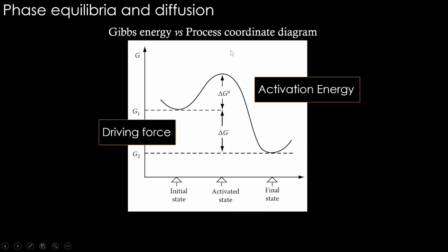Let's say there is a high concentration and a low concentration, and if the atom jumps from the high concentration to the low concentration regime, then the Gibbs energy increases, let's say. If the Gibbs energy increases, the jump is not favored, right? The activation barrier will be really high for that. If that happens, the atoms rather will jump from low concentration to high concentration, because that will reduce the Gibbs energy. Okay, this is called uphill diffusion. We'll see that, and we will see it not only based on the Gibbs energy change but based on chemical potential change. That will be more elegant to understand.